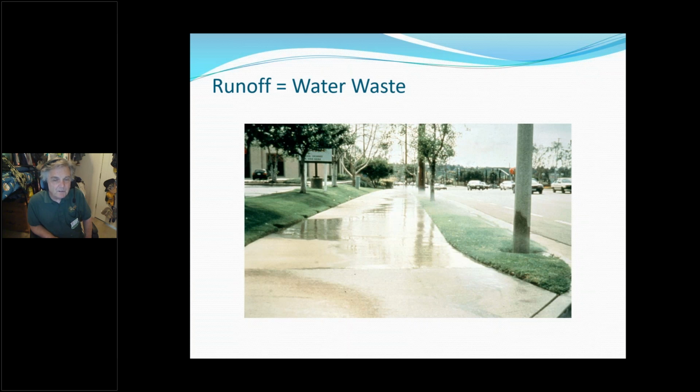We also mentioned that if you have a slope and your water begins to run off, you may have to turn those sprinklers on for however many minutes you can, 5 minutes, 7 minutes, run them, and then an hour later put them on for 5 or 7 minutes. This is called cycling. If that slope can't take the full 15 minutes that it needs at one time, you maybe do 8 minutes and then an hour later do the other 7 so that you don't get runoff. Next.